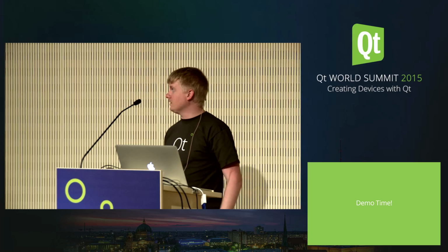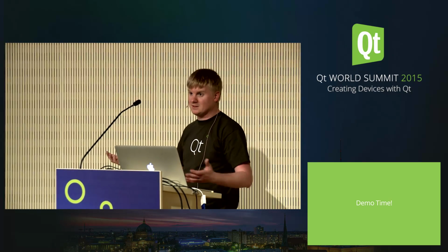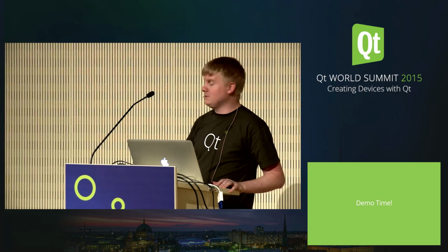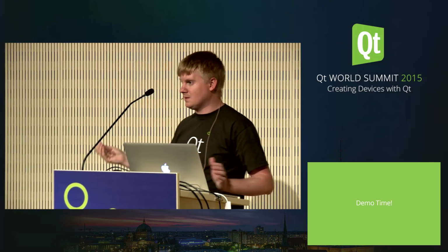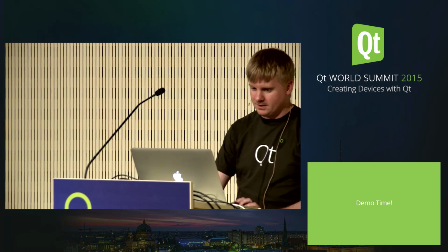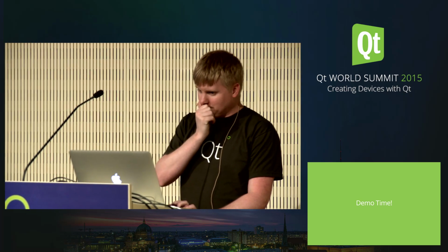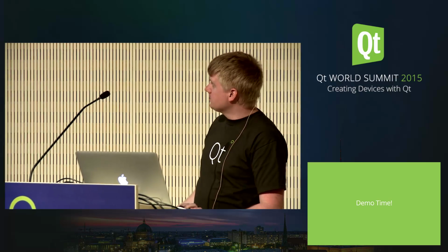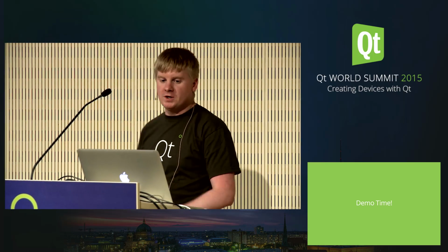In the case of embedded Linux, Yocto or Buildroot will generate the image and the SDK. And you have an image to deploy to, or an existing image to deploy to, like, say, an Ubuntu image running on a piece of hardware. And here, there's a distinction between your host machine and the target image.